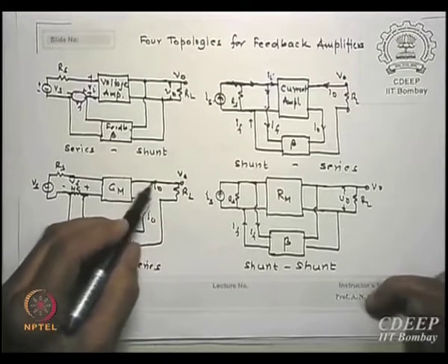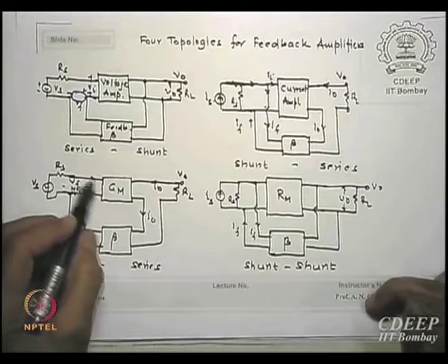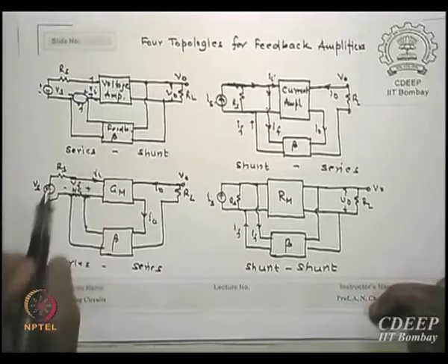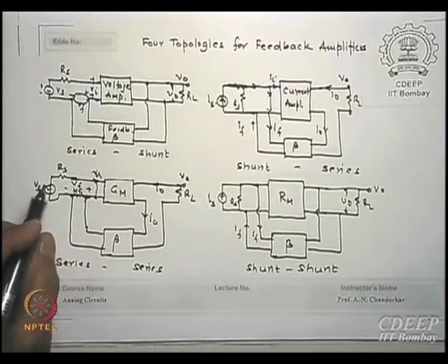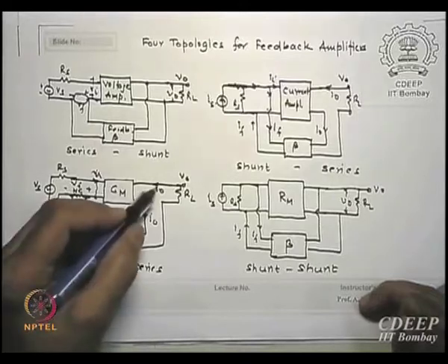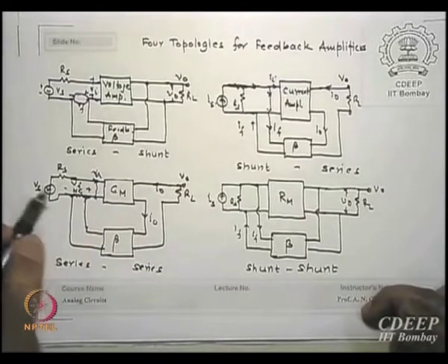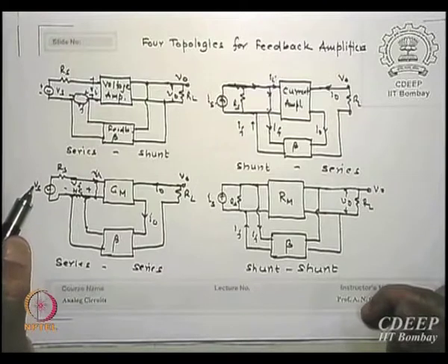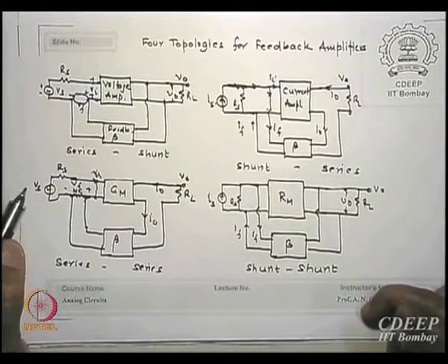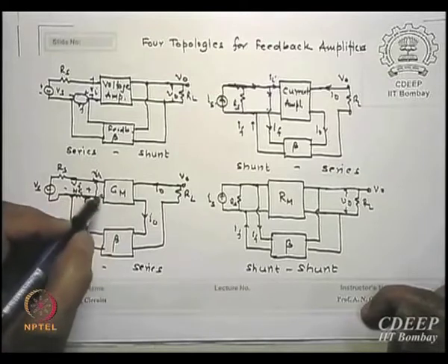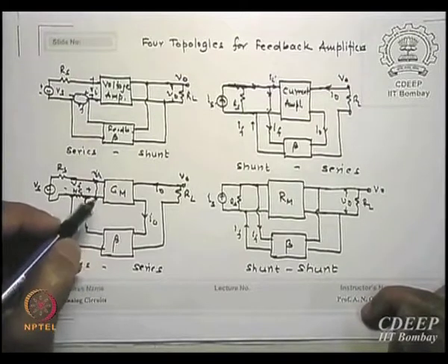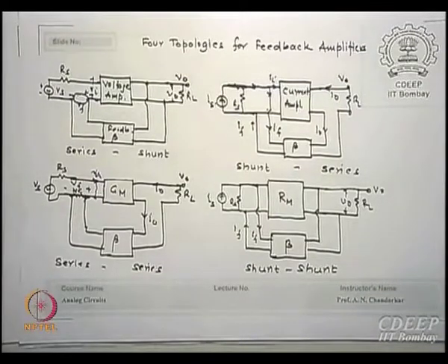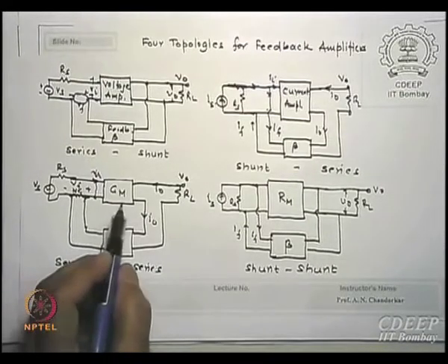Okay. But this amplifier essentially has Io, and Ii is the current flowing here. The voltage across this amplifier is Vi. So what we are now saying is that whatever Io is, it is proportional to Vi by what factor? What is the gain here? Transconductance, current by voltage. So such an amplifier is a transconductor, output is current, input is voltage. So current by voltage is transconductance. Our input is voltage, output is current, so we have a transconductance amplifier and it is given by the term Gm.